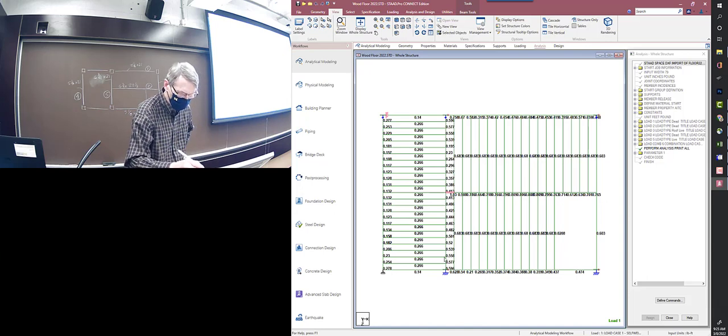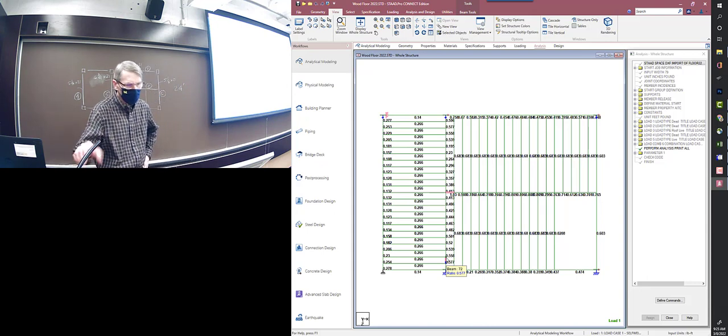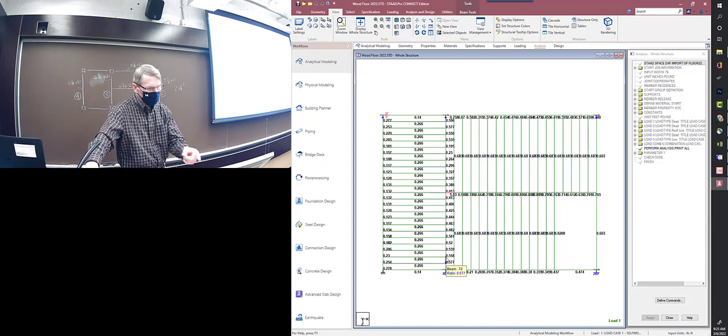On this beam here. The joists, I don't think you could go any smaller than a 2 by 6 and a 2 by 8. Okay, maybe you could try a 2 by 6 for the floor too. But it seems, 12-foot span. Yeah, I'm surprised that it seemed like a 2 by 8 would be more in line with a floor load.